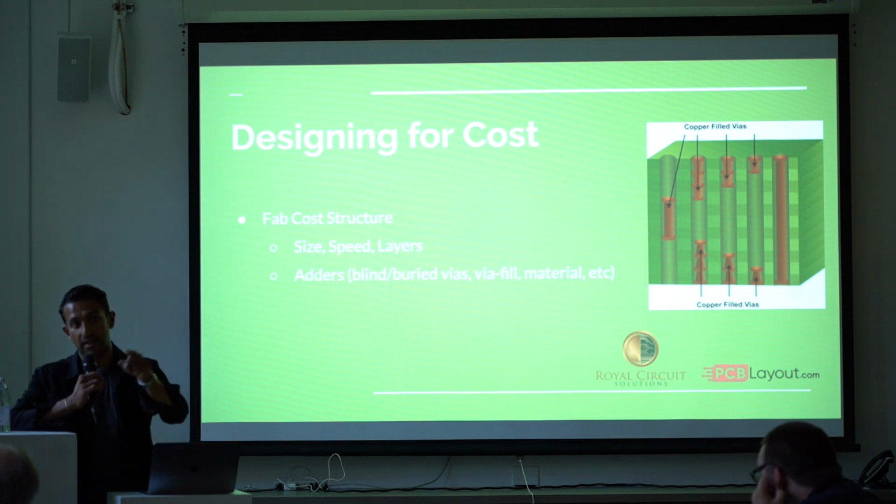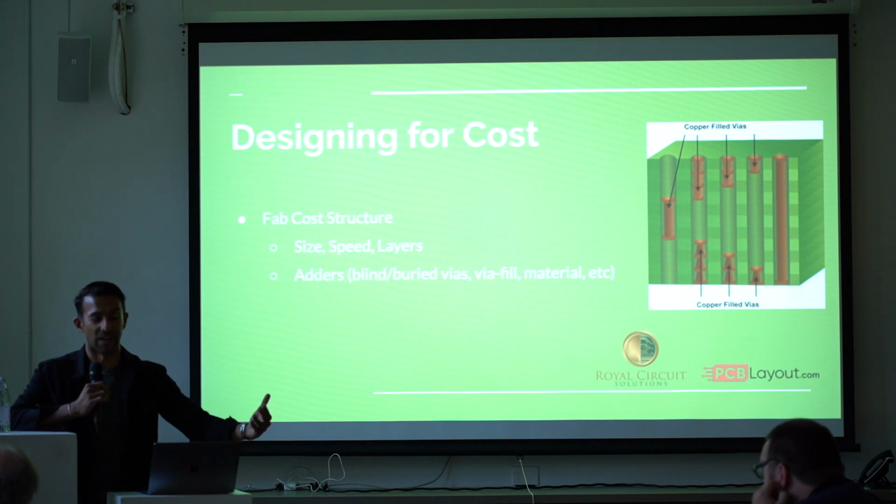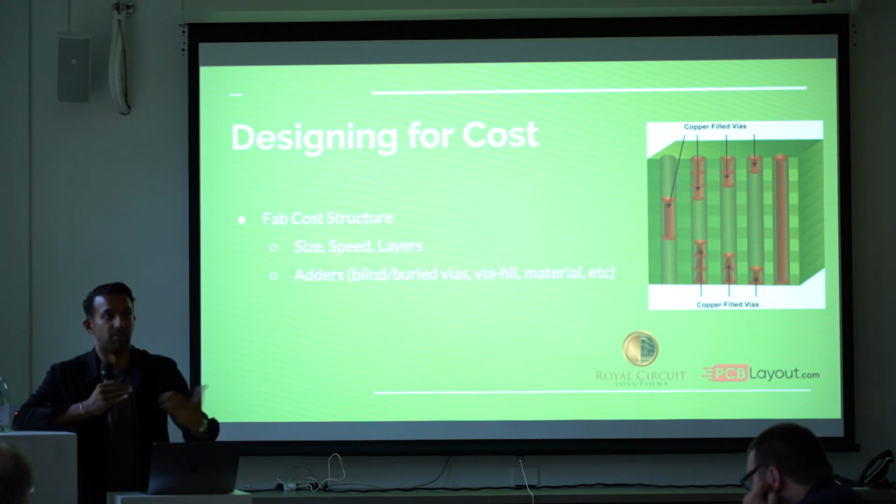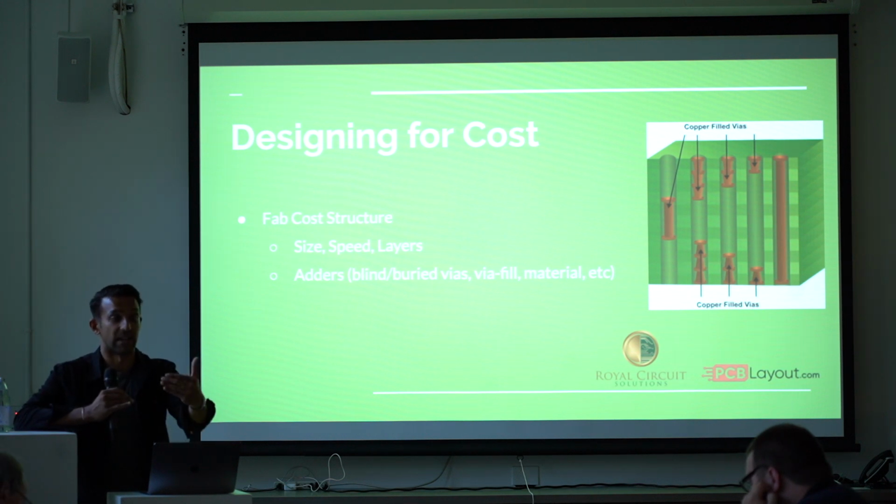Once you go past 10, that curve starts to change because now we have serious capacity issues at the shop. We have 20 panels of your job, but I have 2 panels of another job that I charge you guys $50,000 for, or whatever. And everybody has to get their boards on time. I can't bump anybody else. So there's a premium for that end, but generally the unit cost will go down as your volume goes up.